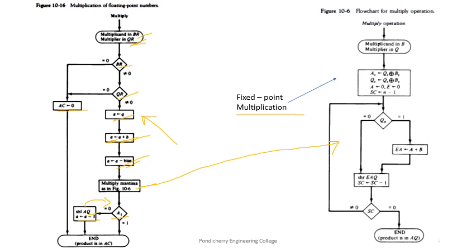Are you getting it? If the smallest operand is 0.1, then the result can only be 0.01. So only one leading 0 may occur in this case. At the most we need only one step of normalization. That's why in this case we have only one shift left, and no continuing loop as in the addition subtraction unit.